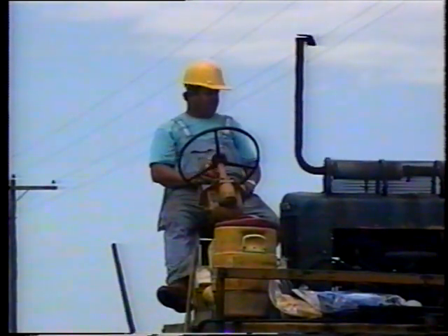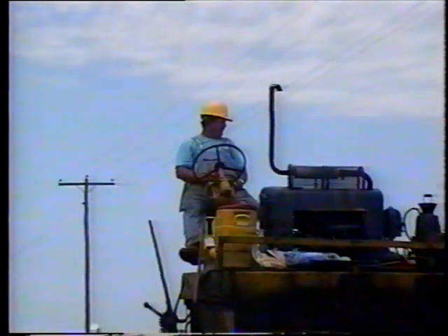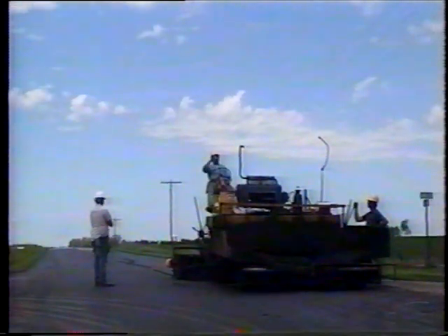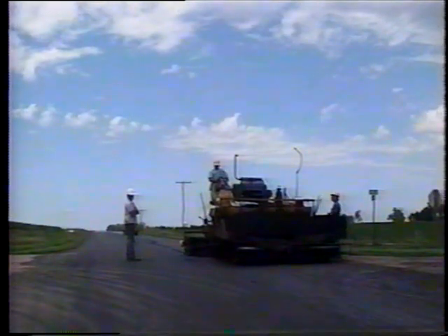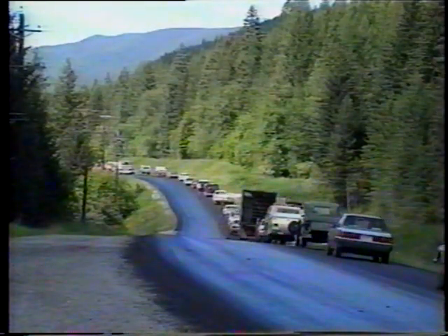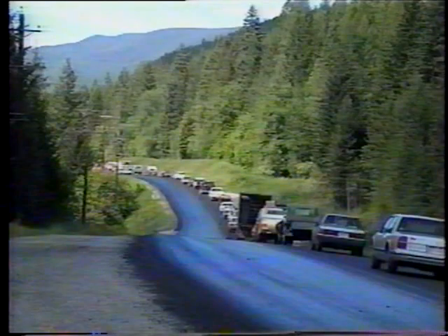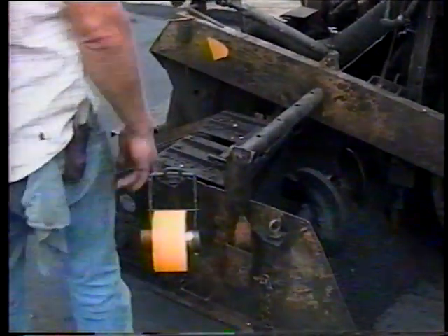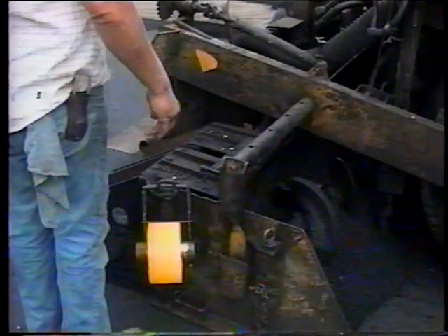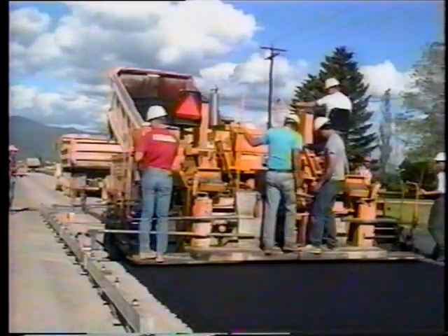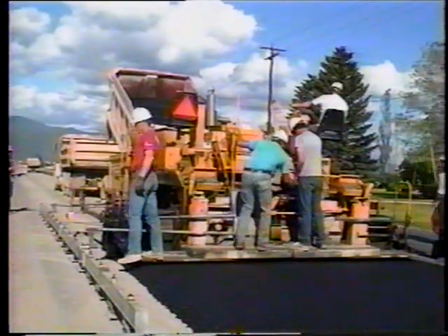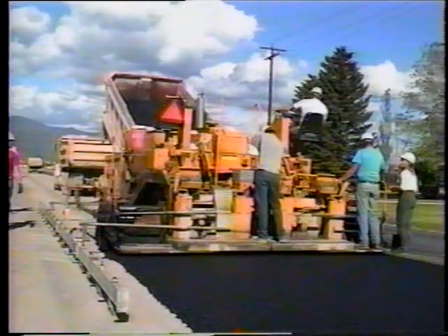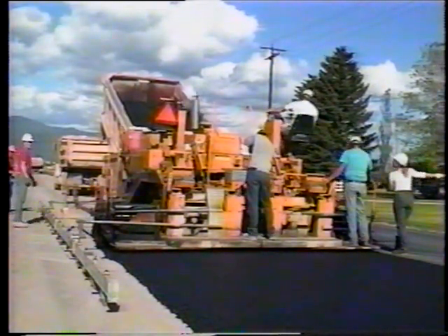Rule number 2 is that rule number 1 is nearly impossible on high-volume two-lane roads. In these situations, even the best efforts to maintain a constant supply of mix to the paver may be frustrated by haul trucks stuck in traffic. The best solution here is to stop the paver quickly when stopping is necessary, and then to reach paving speed quickly when paving resumes. This helps to avoid depth changes and mat roughness as a result of variable paving speeds.